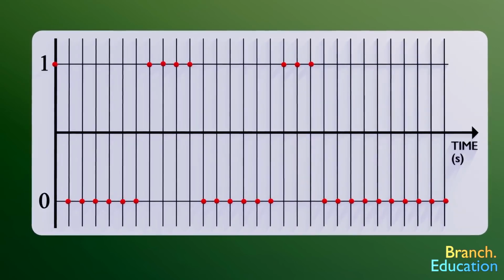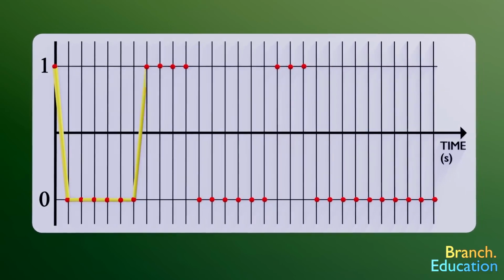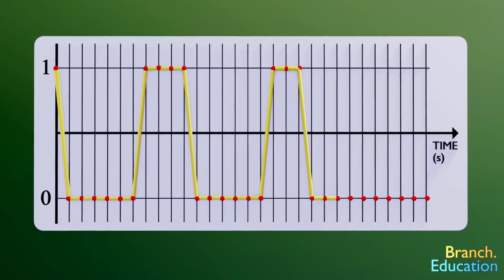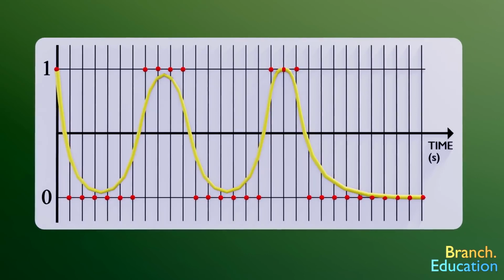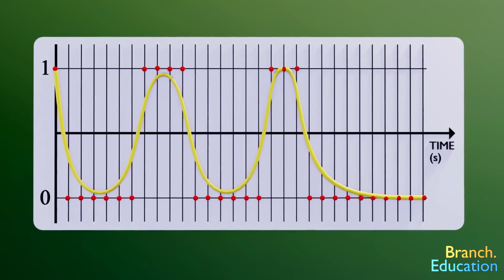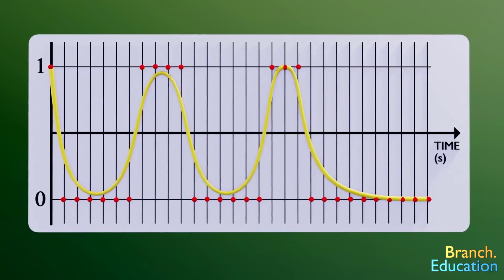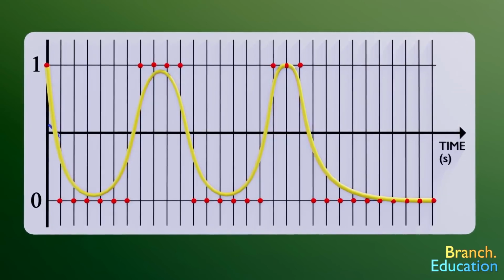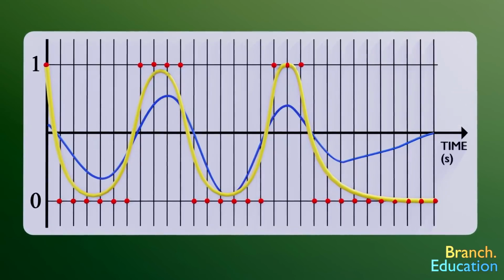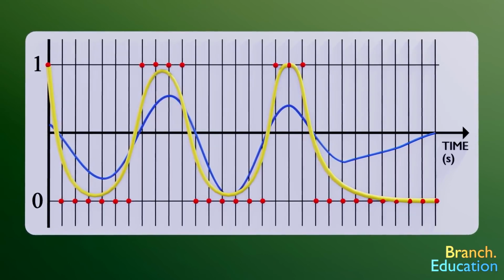But how accurate is our analog to digital conversion? To check, we reassemble the graph using these values, 1's up here, 0's down here, and smooth the line between the points. Now we have an analog waveform created from the digital data, which was created from the original audio waveform, and this recreation looks nothing like the original audio. And thus 1 bit isn't good enough.